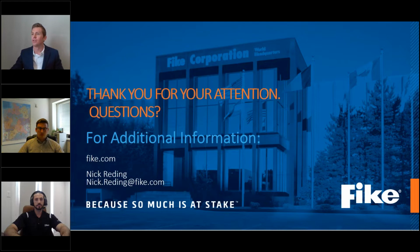So first question is for Giannis. What sort of maintenance is required for a spark suppression system? We need to check if the optics of the spark detectors are broken. We need to check if the machine shutdown is working, and we have to check the nozzles of the automatic extinguishers, whether they are broken or okay. Those are just some parts we have to check in the maintenance.